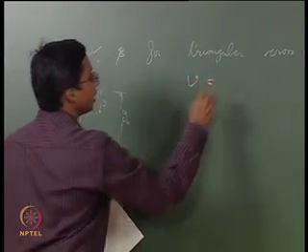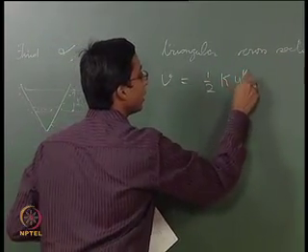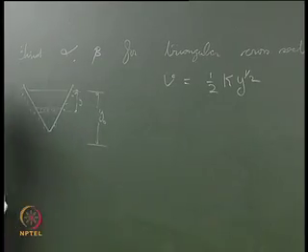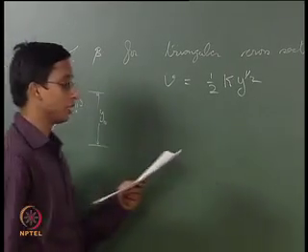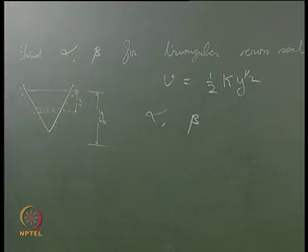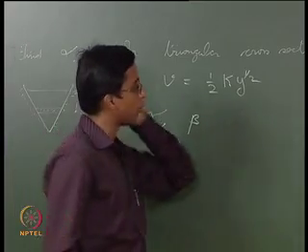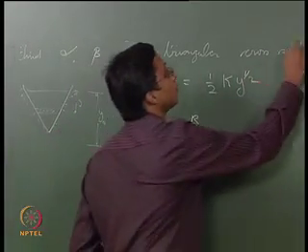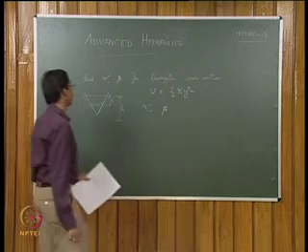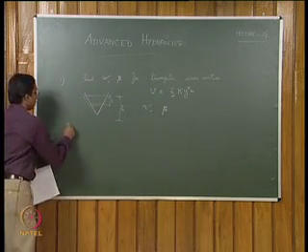Your velocity is here half k y to the power of half. So, you determine alpha and beta. You will be given 1 minute for solving this, and I hope it is quite easy now. You have already worked it out for rectangular cross section, you determine it for the triangular cross section.